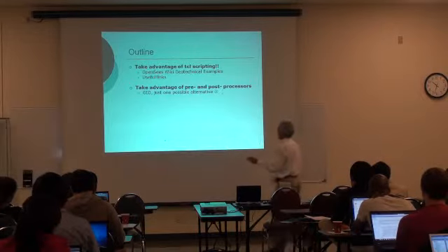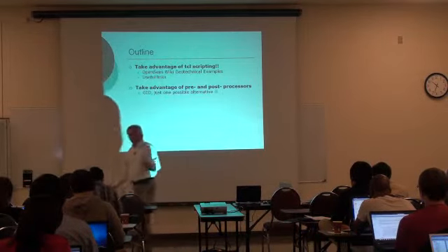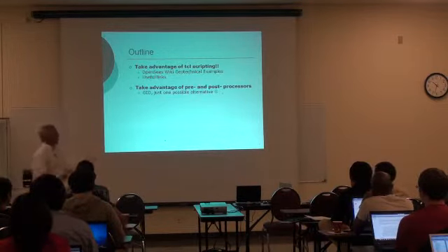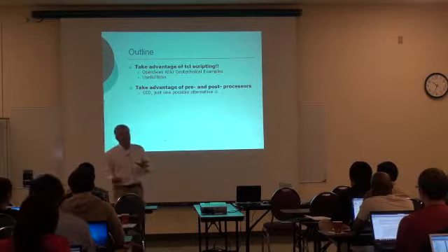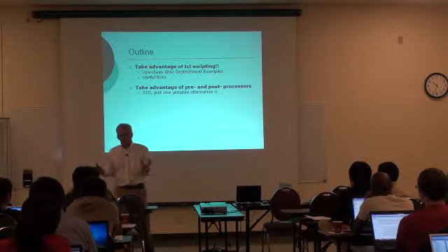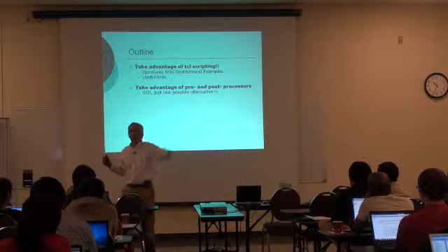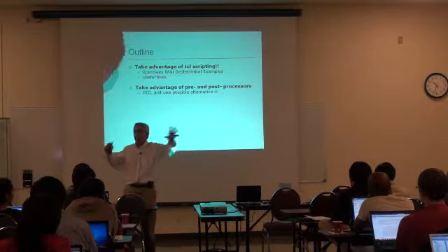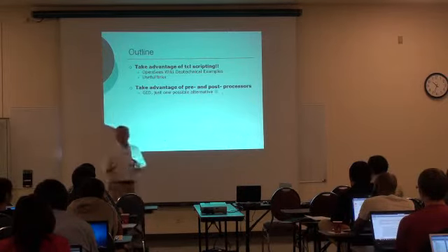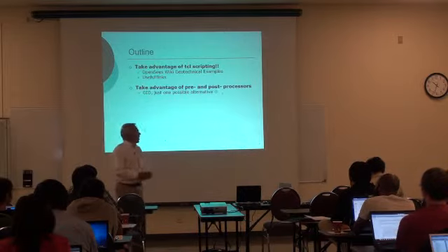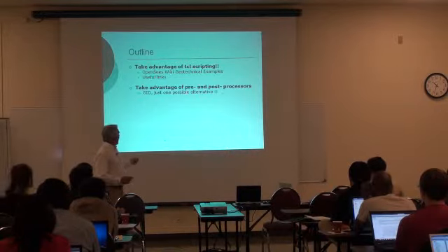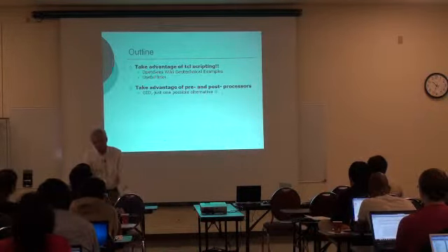The other thing I want to mention is take advantage of pre and post processors. Because as soon as you go into 3D, or when you have a complex structure, you will notice that your MATLAB scripts that are used to develop your frames start to have problems. Because, oh, why don't we do that other building? Well, it's completely different, so your little script that you developed doesn't apply for that building. In soils, it's even worse, because the boundary conditions change completely. So pre and post processors have been developed to help you with this. And unfortunately, OpenSees doesn't have one.